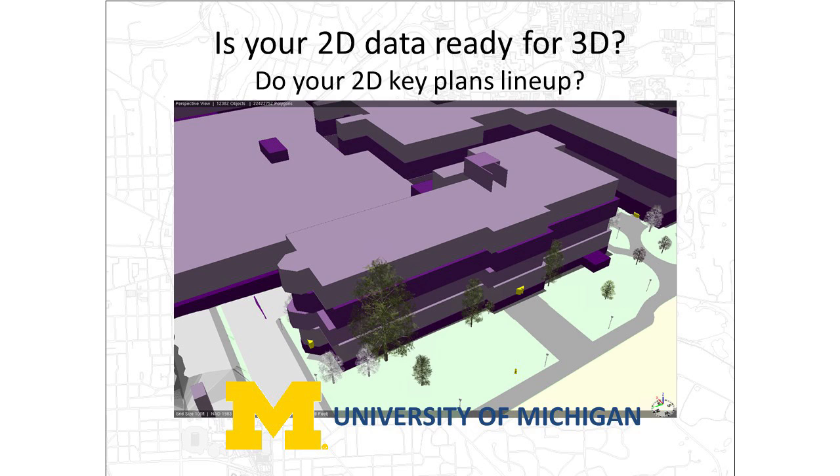The other issue with floor plans is that there's not a good representation for stairs and steps on the outside, and that's an omission on what we have. We're going to have to take and do separate CGA rules for how to take and do the stairs that go up to here, or the ADA ramps to go into the sides and things. They're not part of what our standard floor plans have, so we're going to have to build those separately.